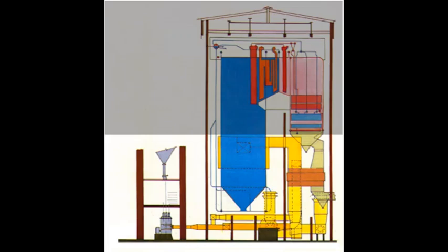Whatever may be the arrangement, we need sufficient air, including the air which will ensure completion of combustion, so that total heat energy can be released through the process of combustion and can be transferred to the working fluid.